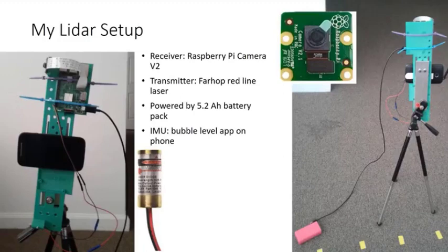The benefit of this design was that the aluminum strip added structural security to the system, but threading the bolt through the tripod mount meant that I could not remove my LIDAR from the tripod without loosening the connection between the two halves. I secured each component to the mount based on how permanent I wanted the connection to be. The camera is secured with M2 screws. The laser was initially secured with an M2 screw until I got it aligned, at which point I hot glued